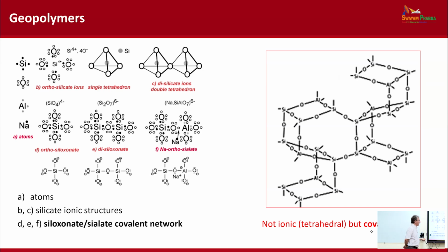In this way, aluminum becomes a network former for a glass, and you form a continuous three-dimensional network where you have only bridging oxygen bonds, and attached to or close to each aluminum ion, you have a balancing alkaline cation.